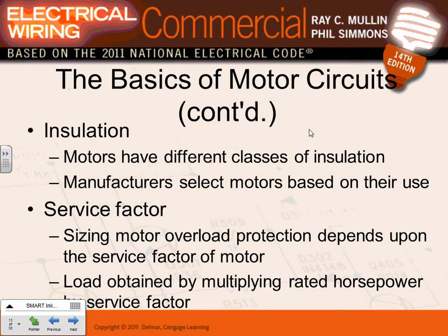Service factor. There's a term called service factor that goes from 1.15 all the way to 1.25. This is how we talked about this one, guys. This is how much overload you can throw on a motor. For example, if your motor is 100 horsepower, you can throw 25% extra on that motor load. So overload depends upon the service factor. Multiplying it by the horsepower will give you how much overload you can put on this motor. Does that make sense? The service factor.